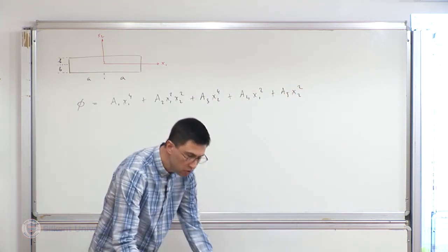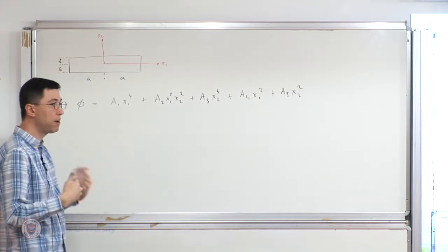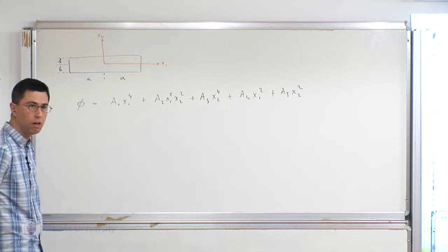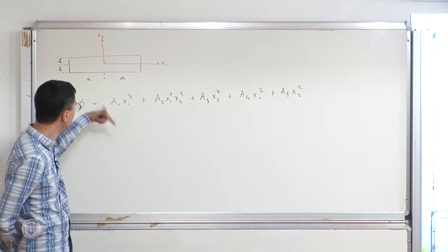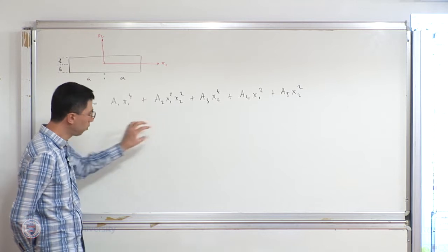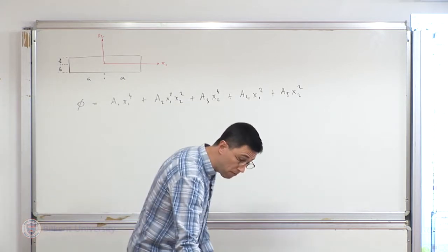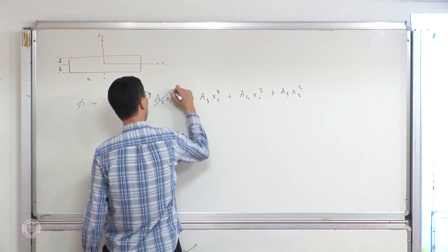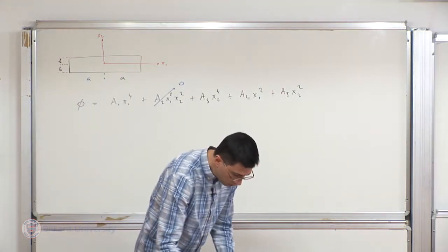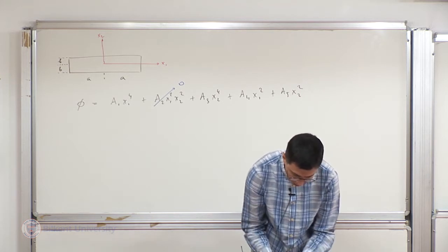With this Airy stress, this is the most possible polynomial Airy stress function we can propose. It delivers a variation of the stresses. It's not a constant. And that variation is an even function of the coordinates because the stresses come out to be 2 orders less. So they are going to be quadratic, and constant terms. And eventually we found what these constants were. And in fact, we found out that A2 was identically 0. So this term actually dropped out. And we were left with the expressions for the stresses.